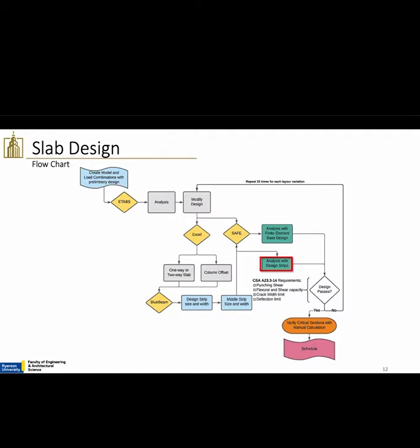The design was then checked against the CSA A23.3-14 requirements, and if it did not pass, we went back to modify the design. If it did pass, we went forward with manual calculations to validate the design where applicable, and proceeded with SAFE scheduling for the rebar. This process was repeated for all other layouts.